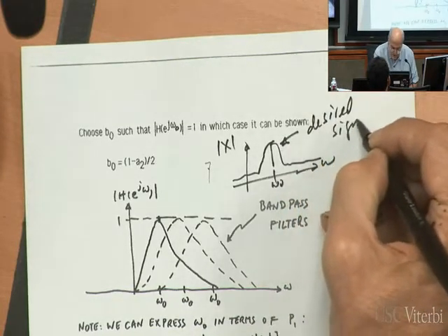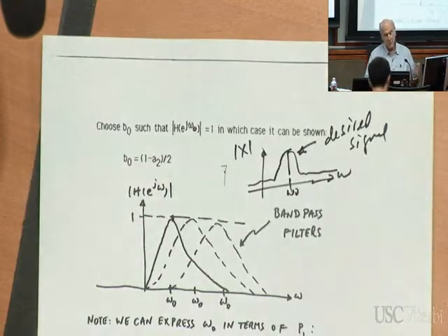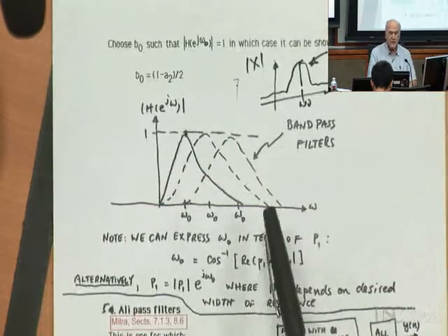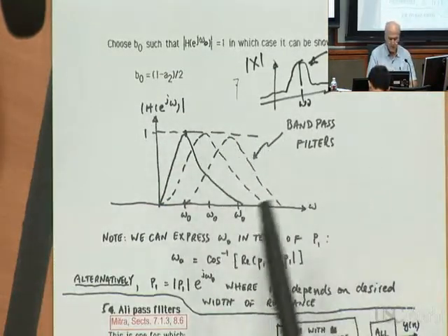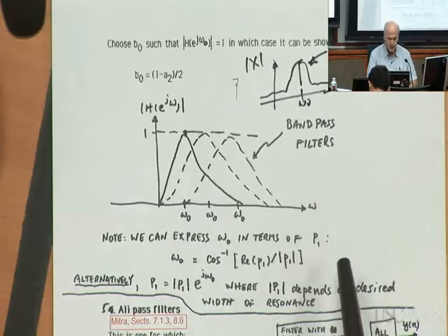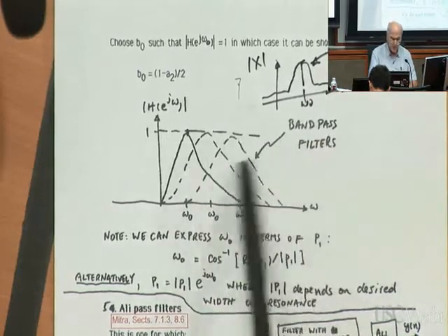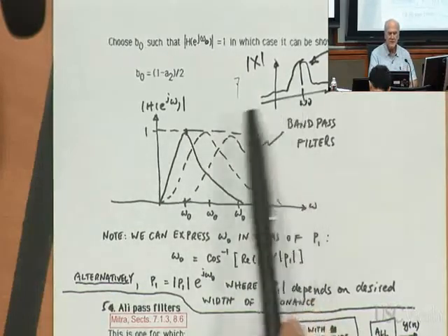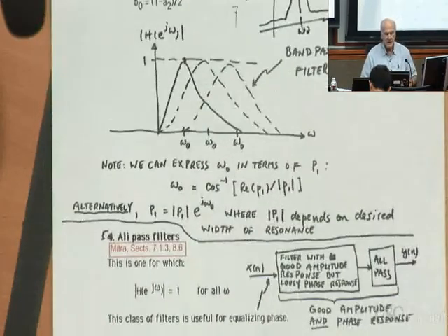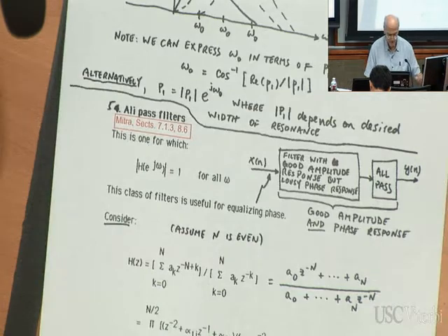Then you would want one of these unity gain resonators, or you could also build a FIR filter, but you'd probably want to consider one of these resonator filters, because you can design the filters depending on your coefficients to attenuate or to accentuate any of these frequencies with maximum gain of 1. And again, in the notes I define all these constants, but since we're not going to use it, I will move on.